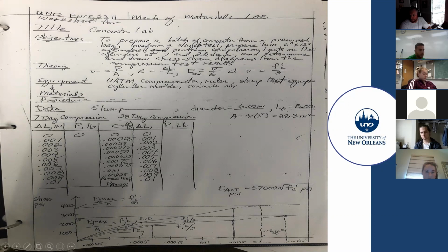And once I recorded the elongation corresponding to the applied load, I have to calculate the deformation per unit length, right? So I had to divide it by the gauge length, which was 12 inch in our case, not the 8 inch. Okay, so let's look at the third equation. It is E concrete, E subconcrete, C-O-N-C. I'm going to find another person.